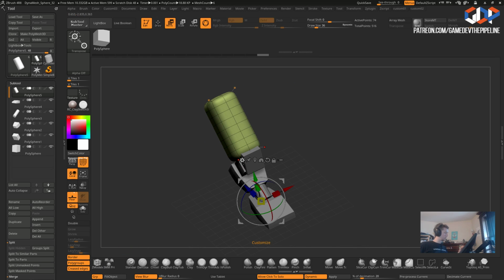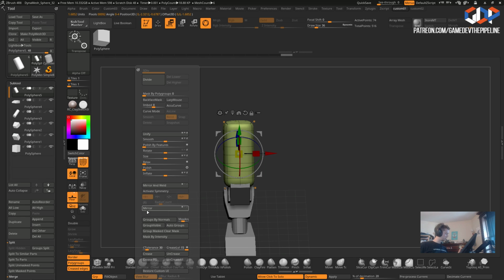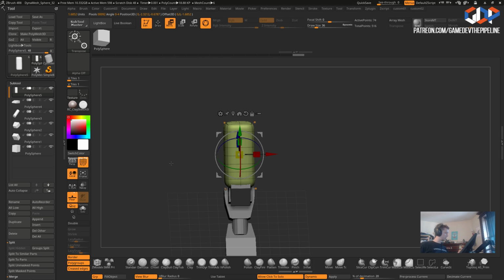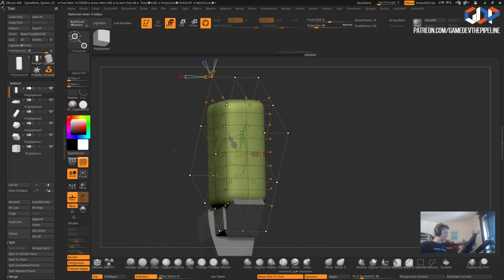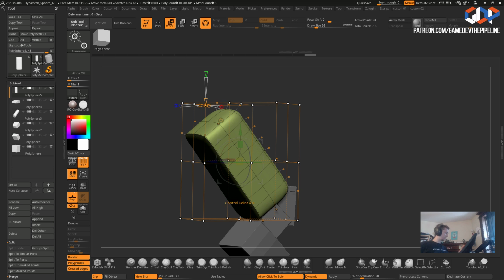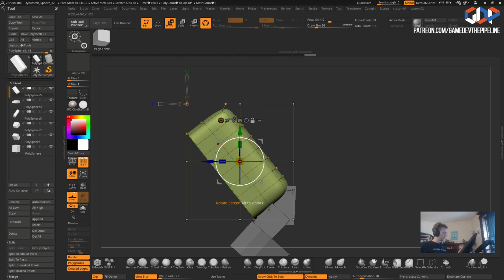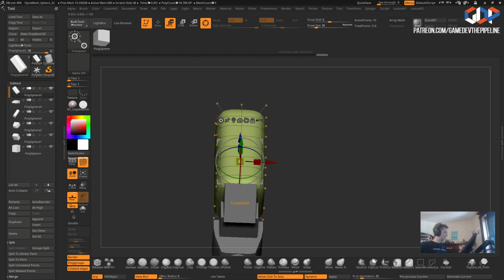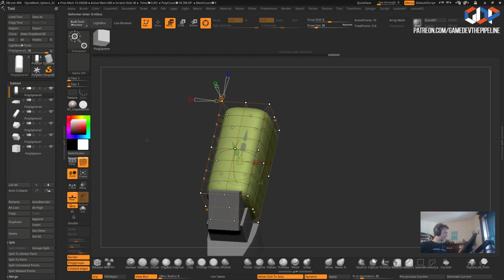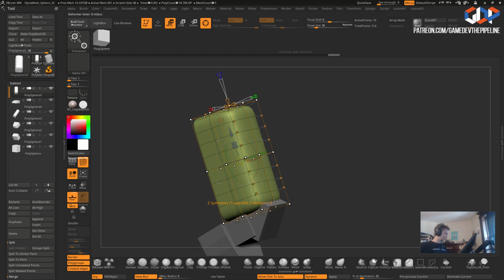Okay, and now center it, disable masking, center it, disable mirroring, and re-enable mirroring. Now, okay, deformer. As you can see, because of my orientation of my Gizmo 3D, it was vertical, so my lattice is also the same way. So from the side view, I'm gonna hold Alt and rotate it to roughly match my shape. And now let's go to the deformer again, and now I have a much better match.